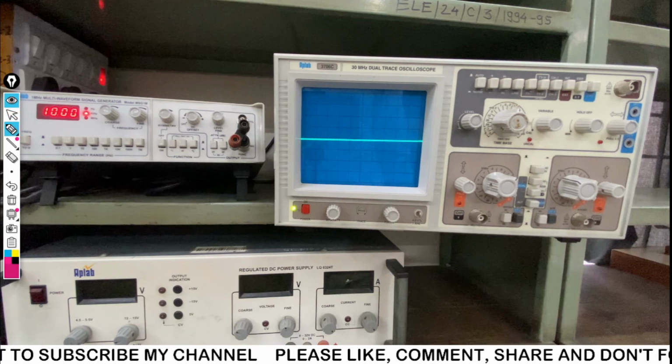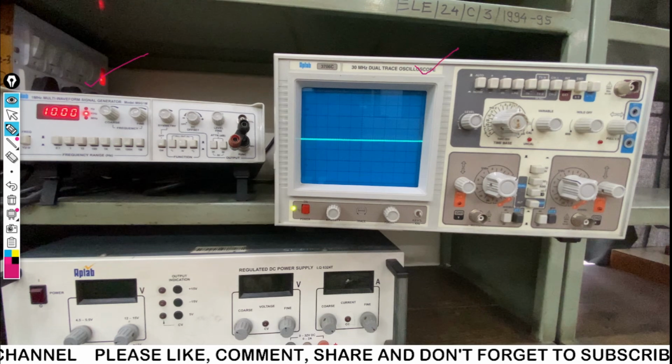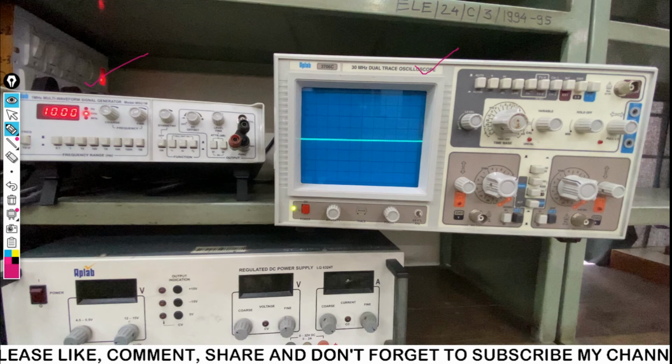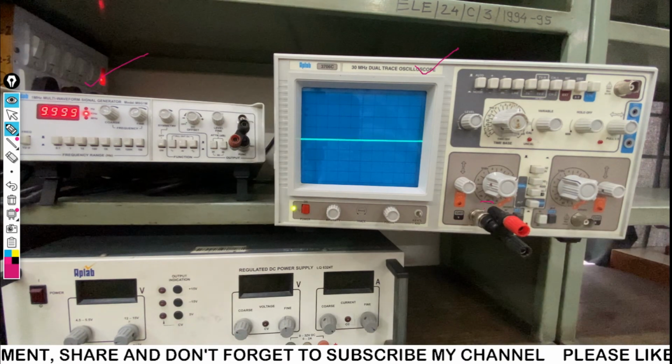You can see here this is the signal generator and this is the CRO. So we are going to connect the signal generator with the CRO. For that purpose, we require a probe that should be connected at channel Y. So I have done it.